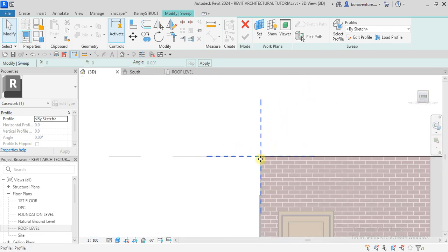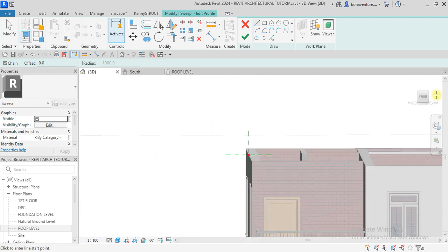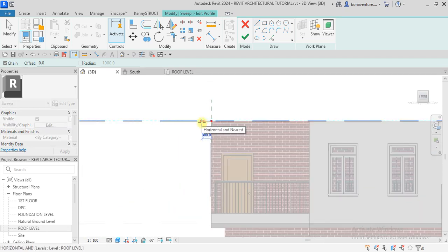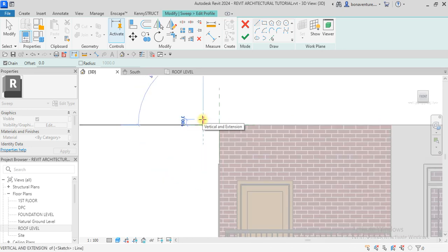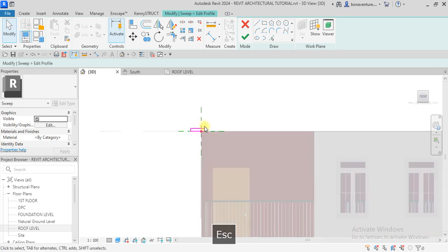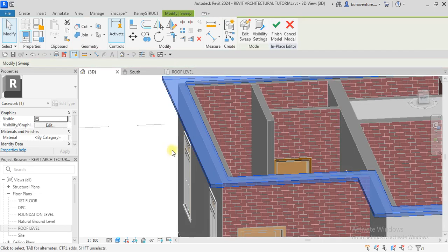Okay, now you remember, the best way is not to draw on your 3D, you understand, but then you can still draw on the 3D depending on what you want to achieve. In some cases you might not be able to draw in 3D. Okay, so very fine. We have this way, this is 300. Okay, and it moves up like this. Let me just say it moves up by a thickness of 75. Enter, and then it moves in a little this way. Okay, so TR to join these two. Okay, very fine. So that when I click on this, it will now move round. Okay, click, very fine.